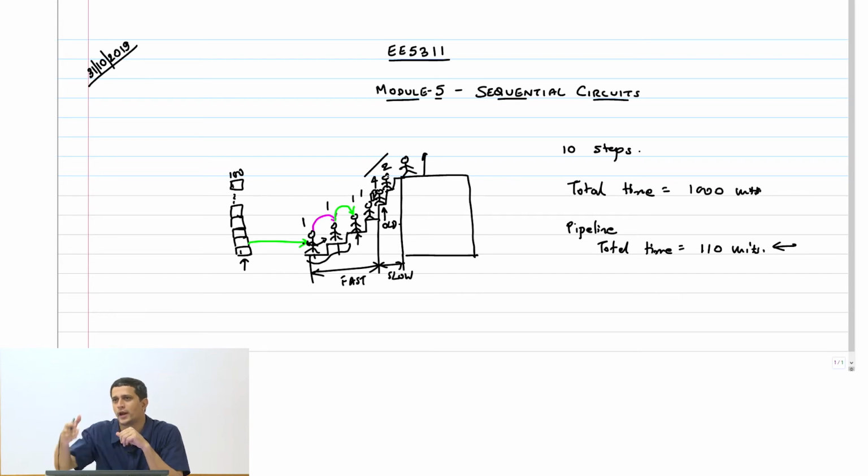It will take 4, 8, 12, so somewhere at 12 maybe you are going to have a problem, or some later time. So therefore, I have to wait for the slowest path in my system before I can feed the next data or the next brick into my pipeline system. The slowest path is basically this 4 plus 2, 6 units of time.